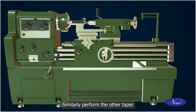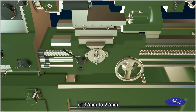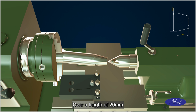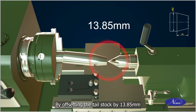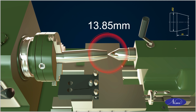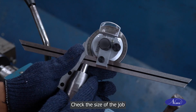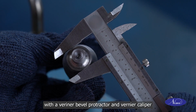Similarly, perform the other taper of 32 mm to 22 mm over a length of 20 mm by offsetting the tailstock by 13.85 mm. Check the size of the job with a vernier bevel protractor and vernier caliper.